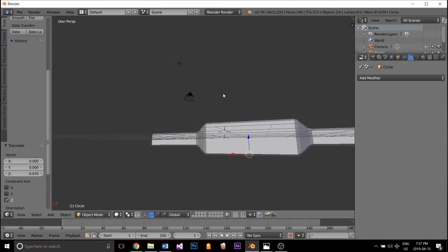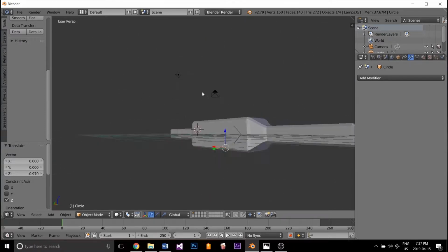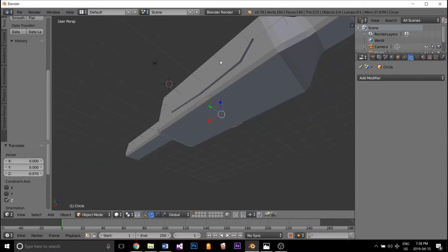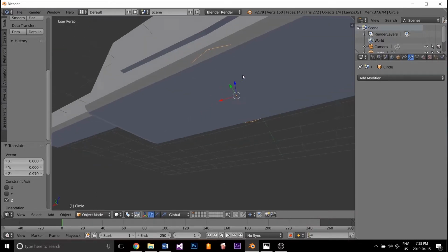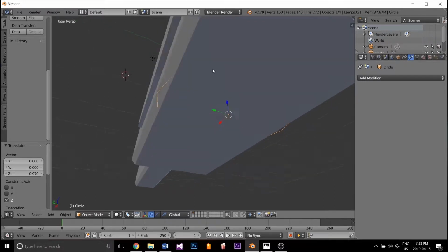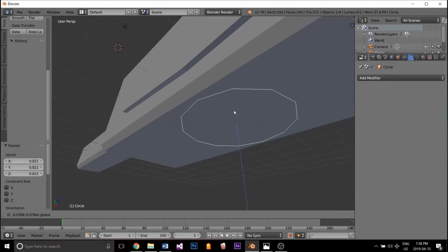To move the camera all different ways instead of just peering around or zooming in and out, shift brings you up and down, shift and scroll, up and down, control and scroll brings you right and left. So when I want to get super close to the object, I just kind of move my way in using the different camera options. From there, I don't want it to be that big, so I'm going to scale it. Going to bring it down.